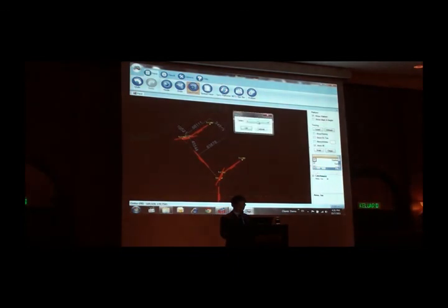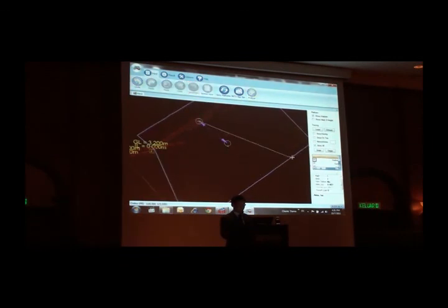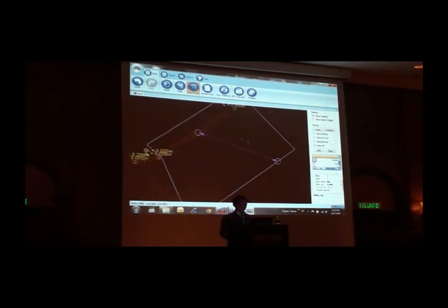For the drain number, you can choose drain number 1. Then this is for the overland flow path, the length. We can always adjust. Then I adjust to the furthest point or whatever. After you adjust it, it will automatically calculate the L for us. And the S, the slope, will also automatically calculate. Later I will show you the calculator.